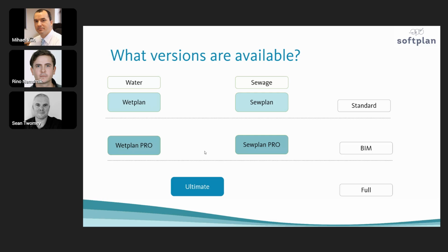You can do some surveying functions and basically geodesy functions, but the great feature about that module is that you can design alignments, and for those alignments you can draw cross sections, which are very similar to road design cross sections, and in those cross sections you can see the real terrain elevations.